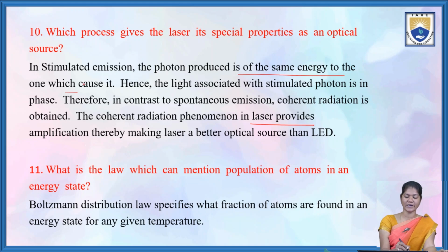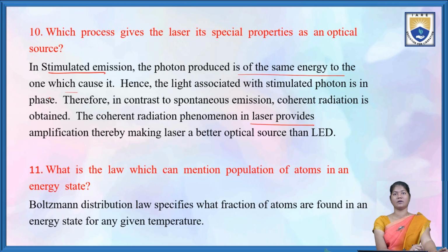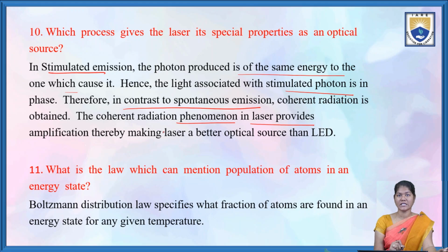So, in stimulated emission, the photon produced is of the same energy as the one which caused it. Hence, the light associated with the stimulated photon is in phase. Therefore, in contrast to spontaneous emission, coherent radiation is obtained. The coherent radiation phenomenon in laser provides amplification, thereby making laser a better optical source than LED.